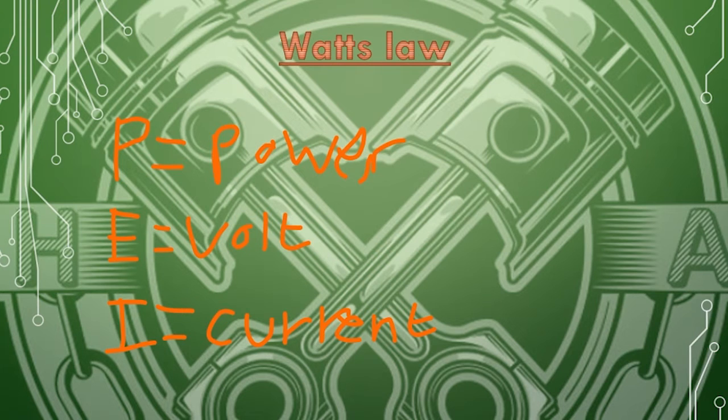Okay, so when it does come to working each of these out, a bit like Ohm's Law, if you wanted to find out the power, you would actually have to times E by I, which would give you the power. And if you were to find out the voltage, you would actually have to divide P by the current which is going through it, and that will then give you the volts.